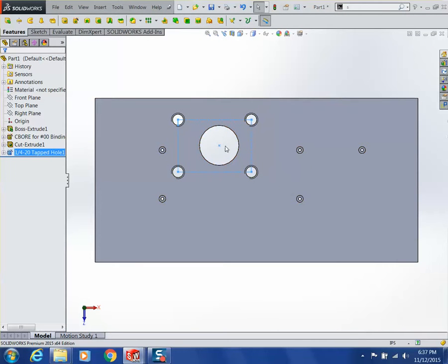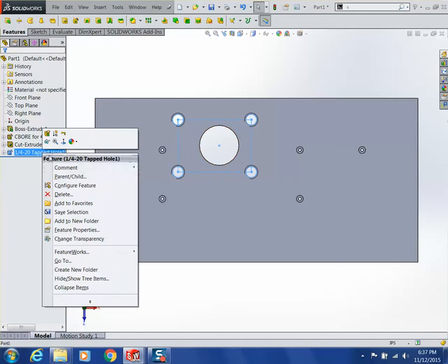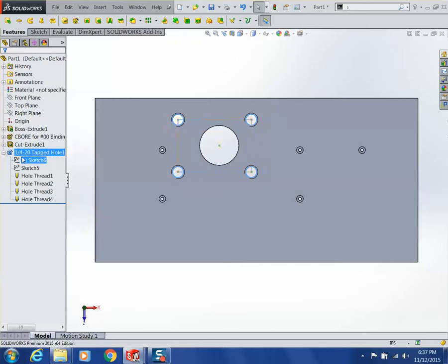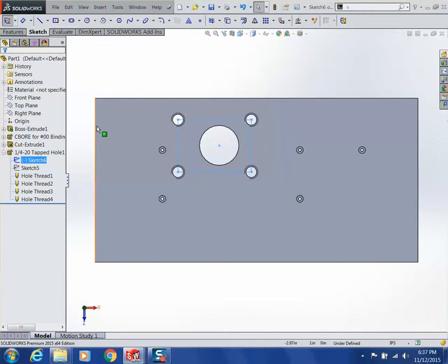And if you go and detail this one later, it would say that there are 5 instances of this tap when there's only actually 4 holes. So this causes some problems later, especially if you go in and start detailing your stuff. So I'm going to go back in and look at our sketch.